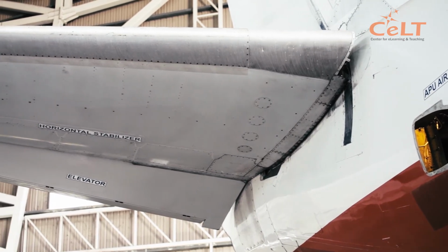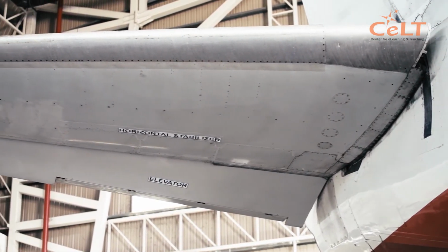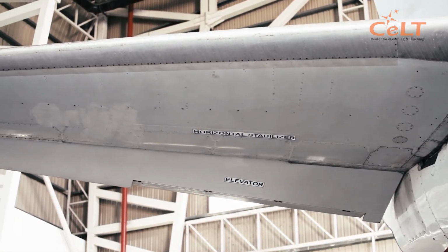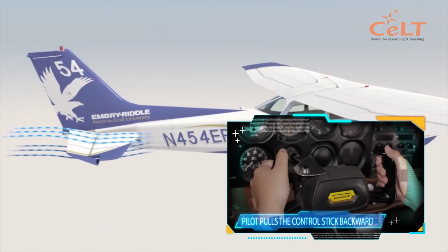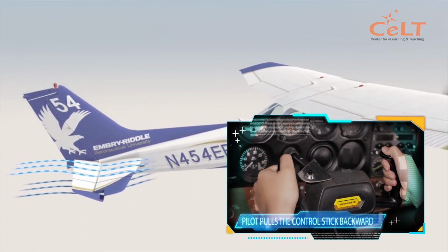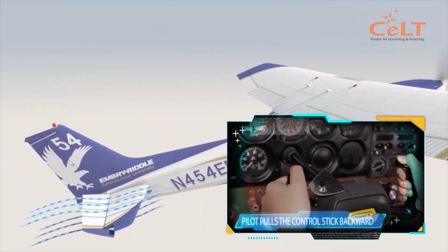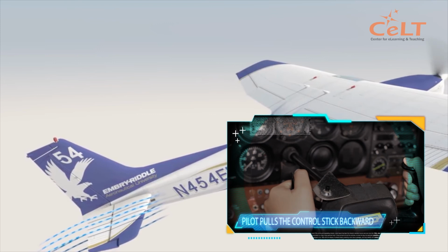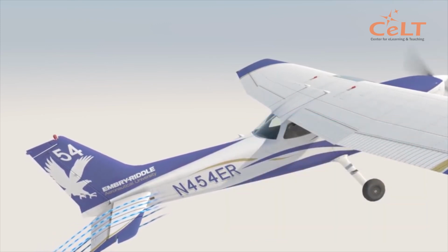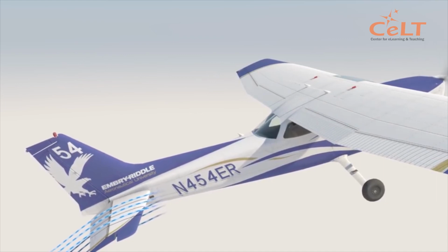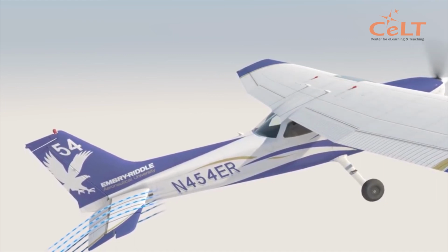Elevators are used to pitch the aircraft up or down, causing it to climb or dive. To climb: 1. The pilot pulls the control stick back, causing 2. the elevators to deflect up. 3. This in turn causes the airflow to force the tail down and the nose up, thereby increasing the pitch